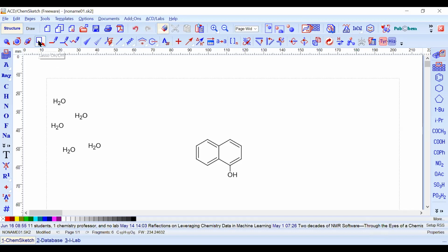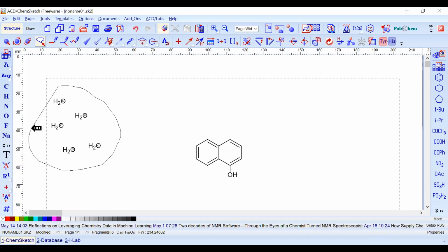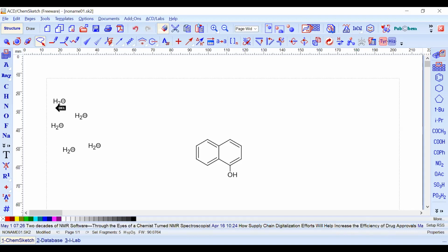Okay, I just click it, come back to my workspace and I draw something like this. Okay, so it gets selected and just go to your system. You have one option called as delete, just delete it, it will go off. Got it? So this is another option for you, lasso. If you have some big structure drawn, as one step you want to remove that structure, you have this option which is called as lasso on and off. So you can use it on and you can delete the existing structure. Another option is this one, that is the delete option, which you can delete the structure.